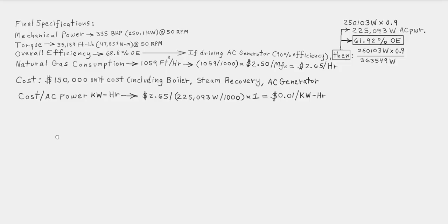It'd be completely solid. And this would also act as a system to actually take heat away from the center of the disc, because it would be isolated from the steam containment unit. And so it's generally going to be warm, but it's not going to be hot. And then it has the ballast weight for increasing moment of inertia. This could easily be serviced, drained, disassembled, and then reinstalled, so the maintenance should be very easy on it.